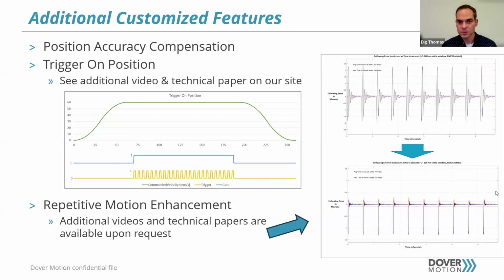And we have a tool which basically goes through and analyzes those moves on the structure and generates a cancellation profile. So think of your noise canceling headphones or something like that. That way, the next time you run those moves, it knows what to expect, and it is able to cancel out that ringing and the disturbances that you do not want.